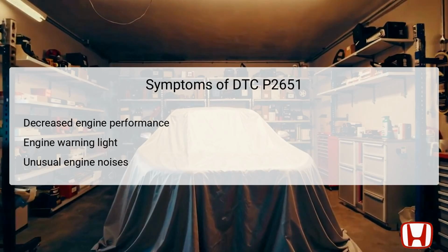Another visible symptom is the illumination of the engine warning light on the dashboard, alerting the driver to potential issues requiring immediate attention. Additionally, unusual noises, such as ticking or knocking sounds from the engine, may occur if the rocker arms are not receiving adequate lubrication. Recognizing these symptoms early on can lead to timely diagnosis and repairs, preventing further damage to the engine.